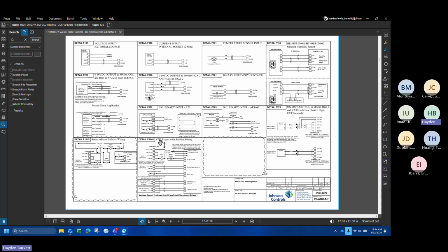Those sensors are, however, mounted right next to each other, and they have been calibrated with a certified meter. So they definitely read accurately. They are redundant to each other, so there's logic in the software that will differentiate between one of the sensors reading inaccurately or essentially unreliably, and then use the other set of sensors.